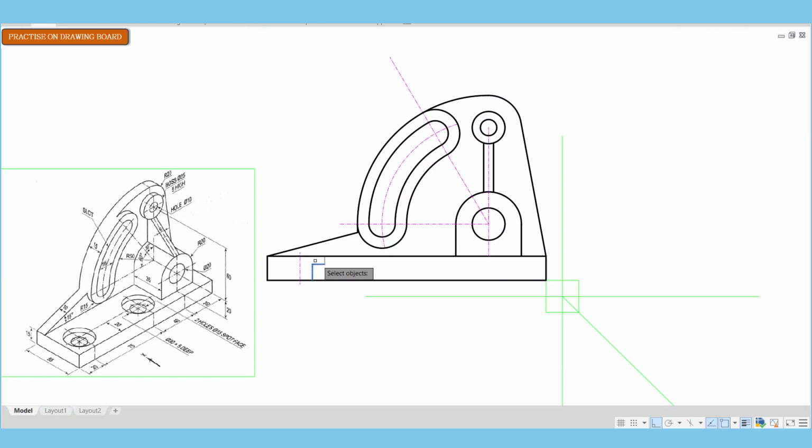And then basically I replicate the same drawing on the other side of the center line, and that will be my solution for the counter ball. And there are two of them, so the distance between the two of them is 75. So you measure 75 from the center line of the one on the left, then you draw the same thing, 75 millimeters to the right of the counter ball on the left, the one we've just drawn.